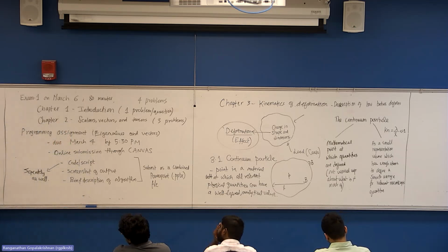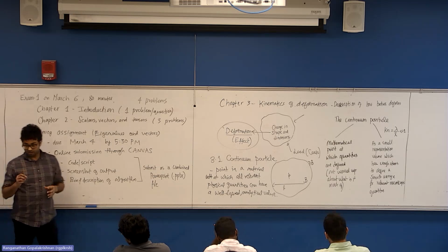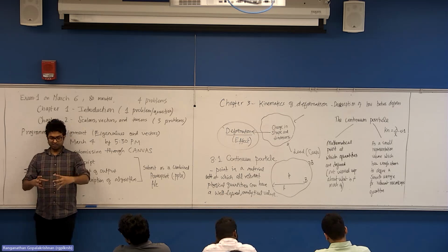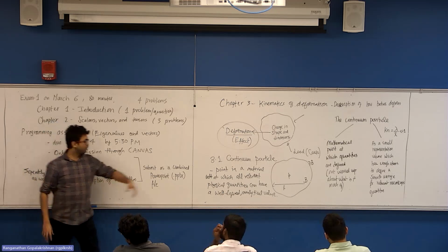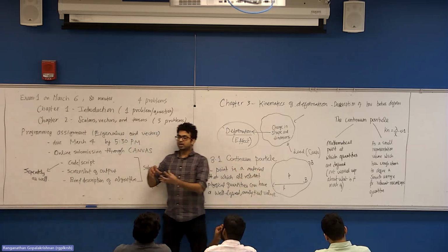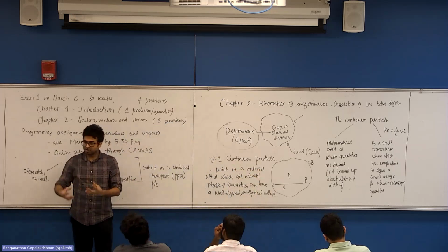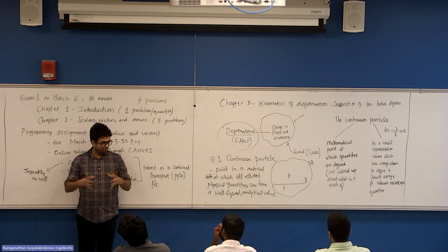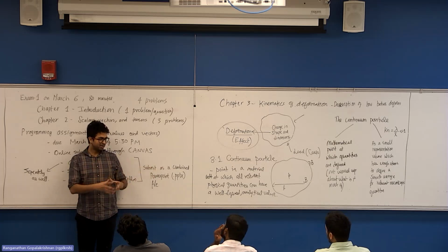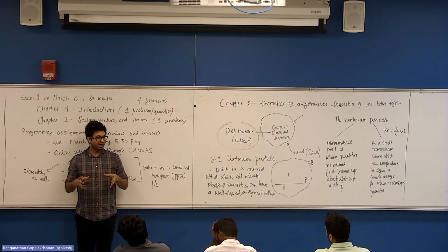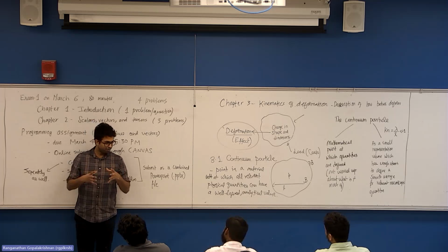They can get closer and further apart than away. So what you're talking about is not the orientation of a single atom. It's like a group of atoms which have a certain configuration. When you apply a load at that point, what you're changing is the configuration of the atoms, making them come closer. That's what I think you meant by shrinkage. It's not the atoms that are shrinking. It is the space between the atoms that are brought closer.